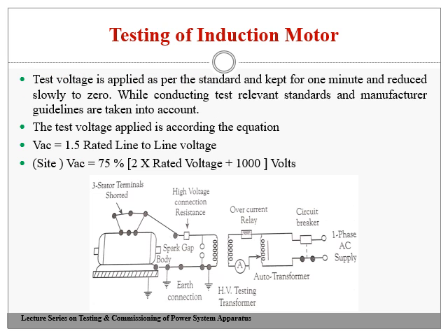You can see in the circuit diagram that we require a single phase supply, and we are going to apply the voltage varying from 0 to 230 V to the high voltage transformer, which can vary the voltage from 0 to 60 kV or maybe 0 to 150 kV. It depends upon the high voltage transformer capacity. You can see that all three terminals are shorted and connected to the HT terminal of the HV transformer.